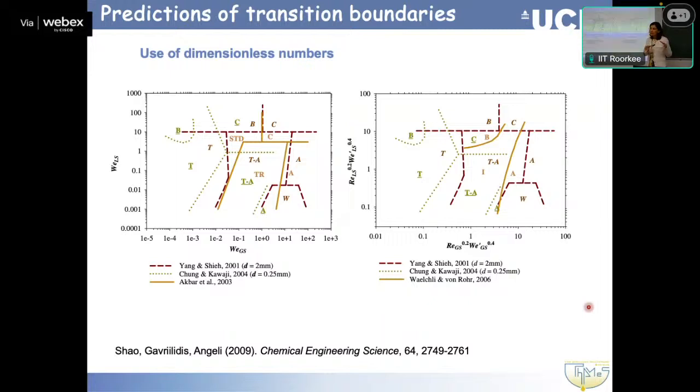Most of the work has not been done based on the inlet conditions, it's based on what people see in the main channel, but the inlet can play a role. And what I'm saying is that it's even more important in small channels, not only because the inlet can be quite comparable, but also because the development lengths are much shorter in small channels than in a proper large scale system, thinking of pipes, for example. So if people are interested in doing work, this is an area where people could do a lot more work. So it's always worth having it in mind.